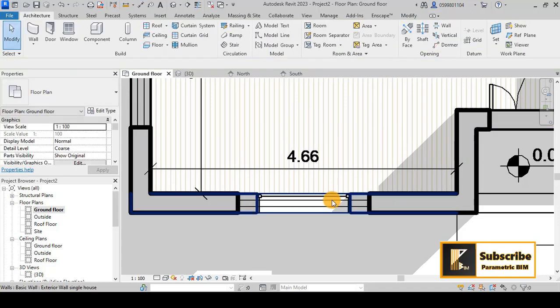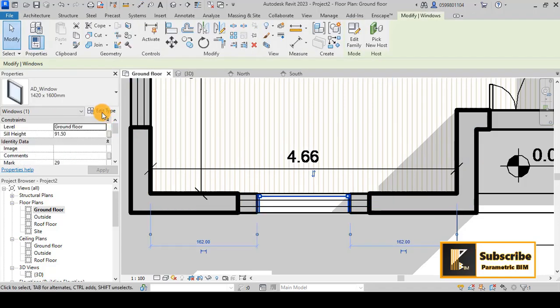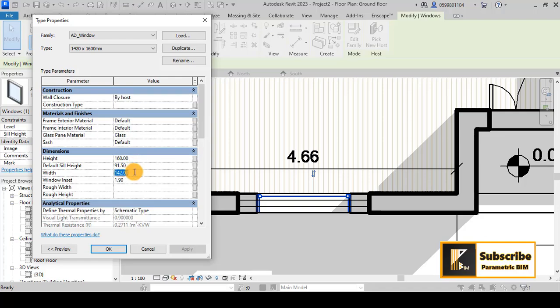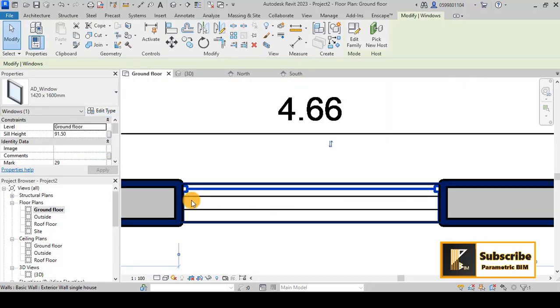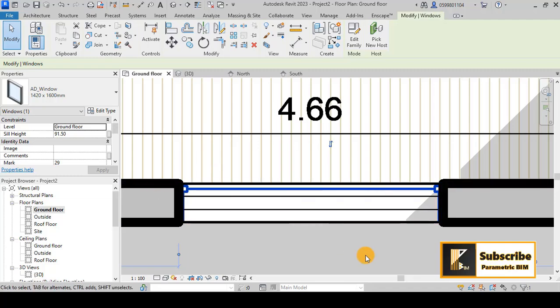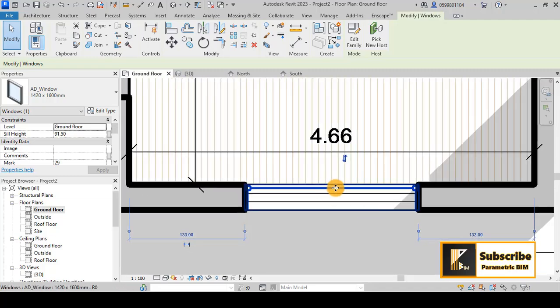So I will go back, click on the window and edit type and give 200 centimeter for the width. And as you see, our window automatically came with the window that we have.